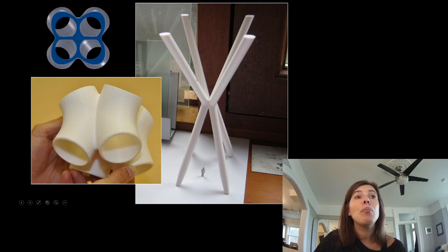But how do you pump concrete into this object? And concrete cures, so there's shrinkage. They were able to deal with that at the top by some smart detailing, but how do you deal with that two more times here? So it needed to be hollow to allow concrete to be pumped from the bottom and pressurized up to the top. So these needed to be openings here.